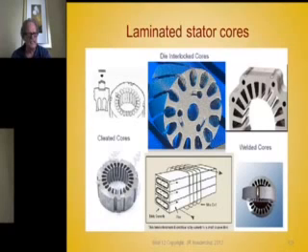This is a cleated core. There's a notch punched in the OD, and then this steel. They're stacked on tooling and arbors, and then this cleat is forced in there and kind of flattened with wedges itself and holds the thing together. This example shows the effect of eddy currents and why they're laminated, but here's a strap over the OD that clamps it.